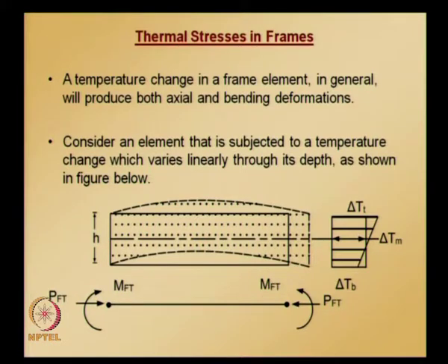temperature changes of top and bottom surfaces, we expect the element to experience some curvature. Because of curvature, moment will be developed, and in addition, if the ends of the frame element are constrained for any movement, that is they are totally fixed, then fixed end moments will be developed in the direction shown in the figure.